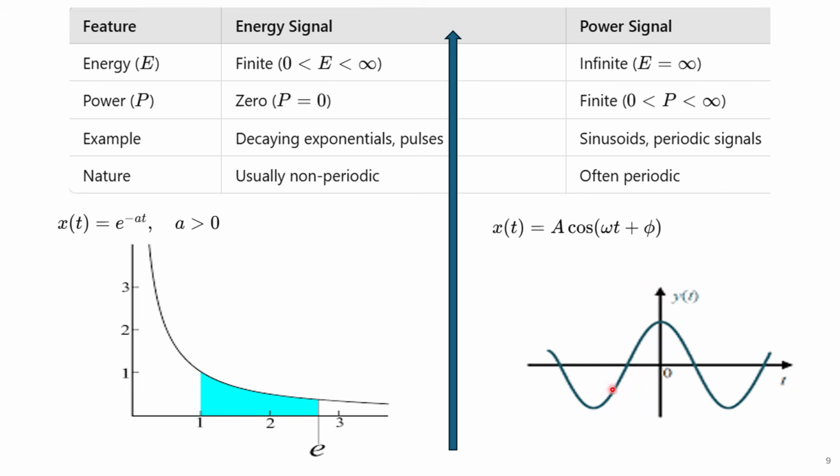And similarly, the sinusoidal or any cosinusoidal signals are all examples of a power signal. Why is it so? Because the time period is, suppose, 0 to 2π for a sinusoidal or cosine function. If you observe the power for only one time period, then it will be finite, right? For only one time period, not the entire one, and energy is for the entire time period, so that is infinite, right? So in this case, power is finite and energy is infinite.